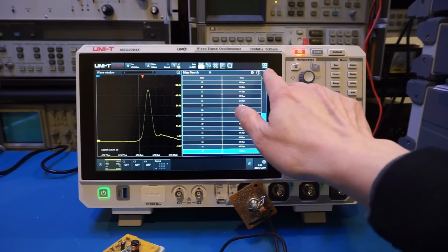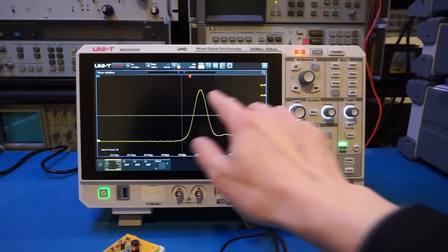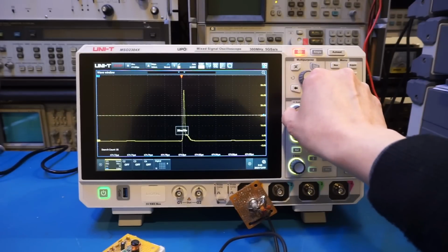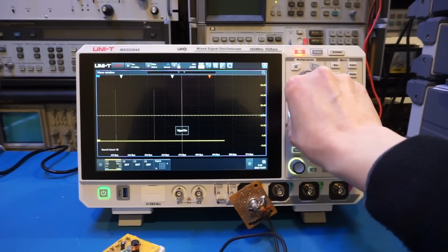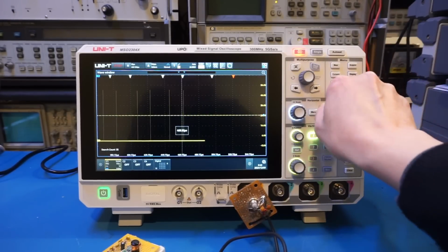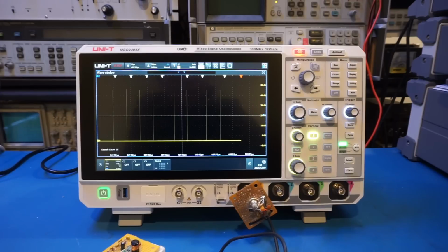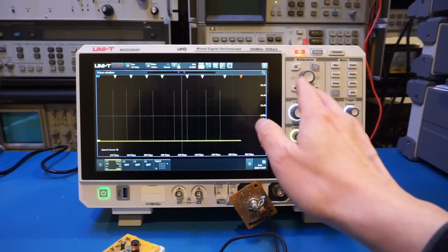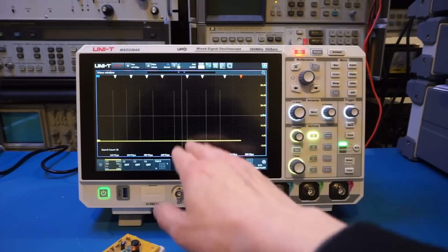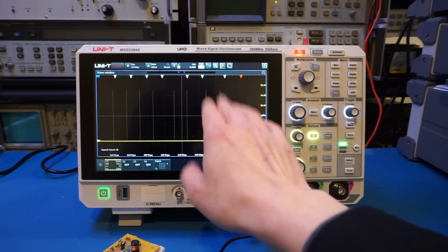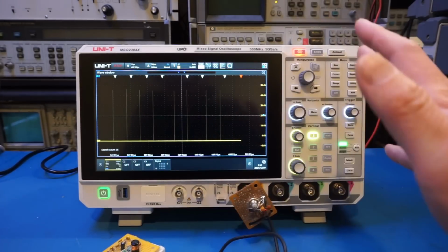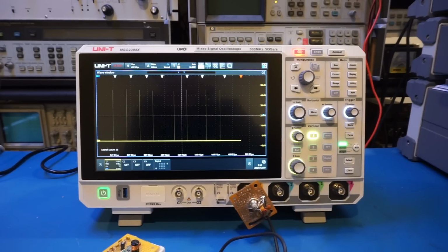You can see that if I just close this, we have this very short signal here. And if I zoom out, you will see we are actually not capturing that many signals here. You can see that the sample memory essentially is wasted, as for the majority of the time we're just waiting, there's nothing happening. And we do capture the signal here and there. So can we do better? The answer is yes. To solve this problem, many modern digital scopes have the segmented memory mode.